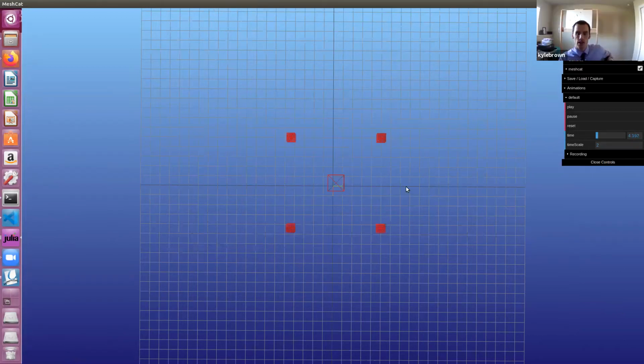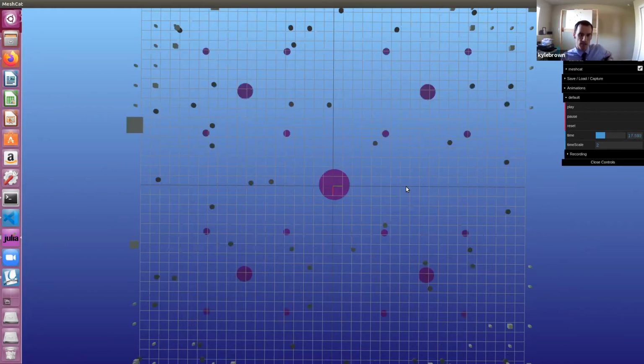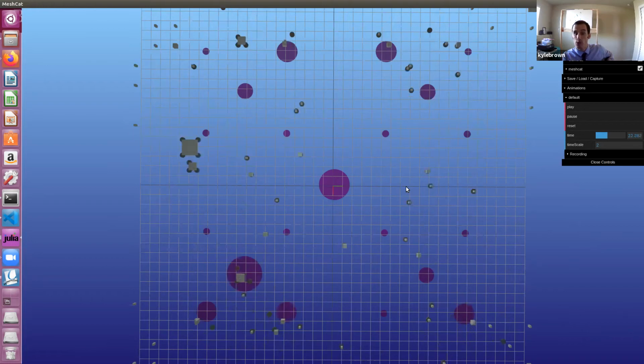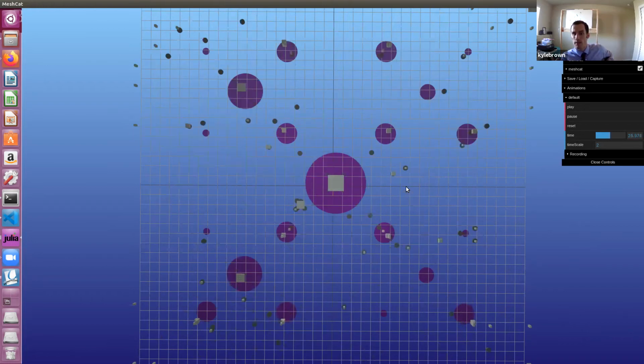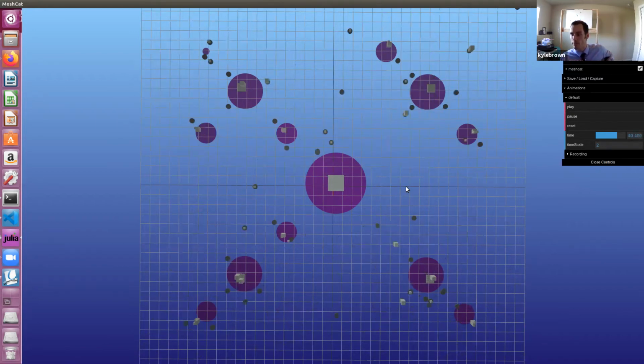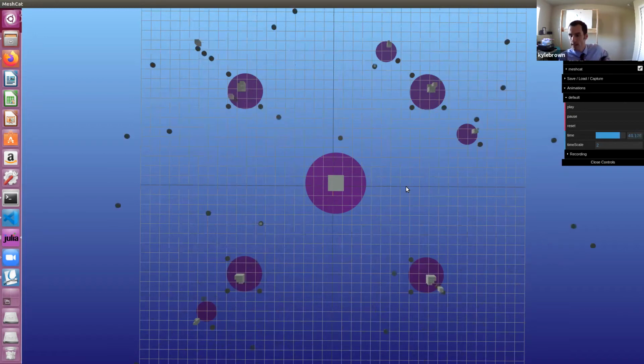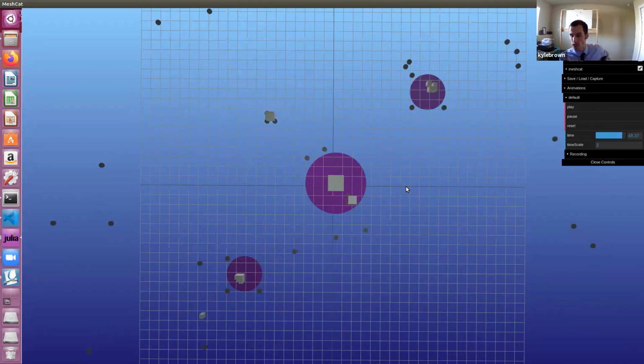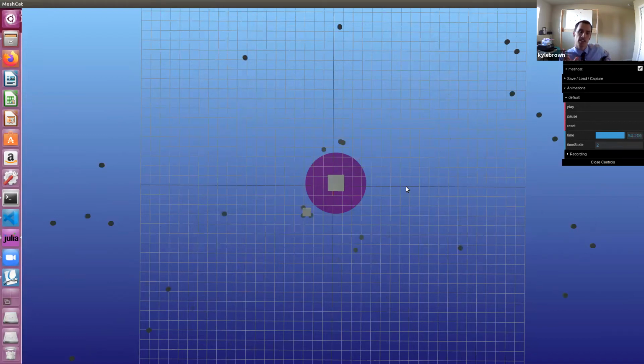So basically the idea of the nominal controller is to give a planned velocity for each agent that will get it to its goal. And we've also imposed the restriction that robots need to go around in the clockwise direction so that there will be fewer collisions that are caused directly by the nominal controller. That said, there are still collisions that occur, as you can see. I was just trying to say that we've made a few design choices that hopefully reduce the amount of collisions that occur directly because of the nominal controller.